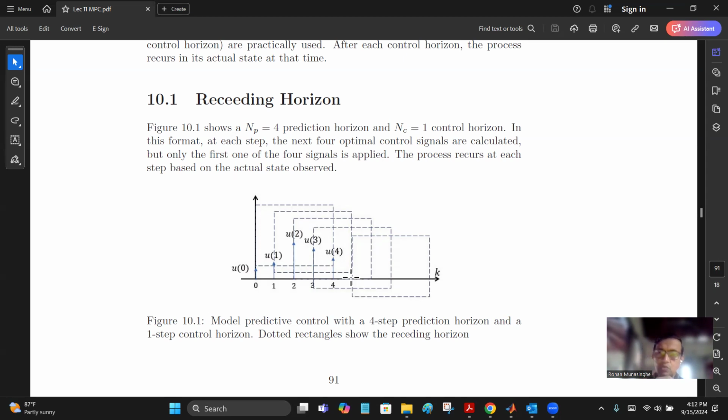If you let the system move on without correcting for far too long, errors would be very big, and you lose your performance and optimization also. So, not to lose the grip on the control of the plant, we do not keep implementing the control signals from the optimal sequence, but we only implement 1 or 2, and then reassess and recalculate a new optimal control sequence. So this way, it becomes feedback in real time.